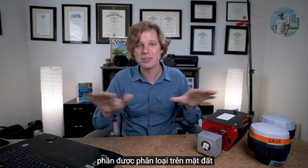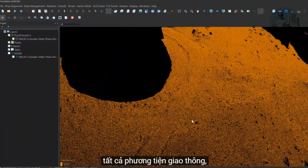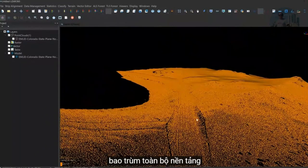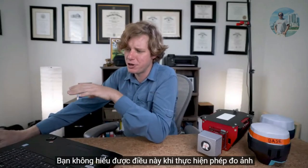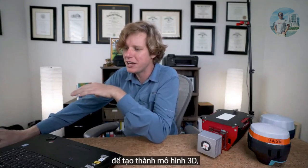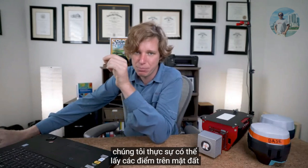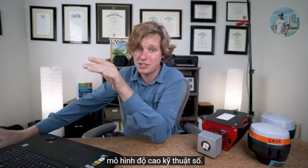Let's go ahead and look at the ground classified portion of the LiDAR data set. This is stripping off all the trees, all the vehicles, everything that's not ground. And you can see there's an incredible amount of density of data outlining all of the ground throughout the entire data set. This is actually what's unique about LiDAR data. You don't get this doing photogrammetry, because when you do photogrammetry, which is photos, and you stitch those together to make a 3D model, you have all the trees, and the trees are just blocking the ground, and you're not seeing the ground really well. But with the LiDAR data, we're able to actually get points to the ground underneath the canopy of the trees. Then from this is what we're going to derive the digital elevation model.